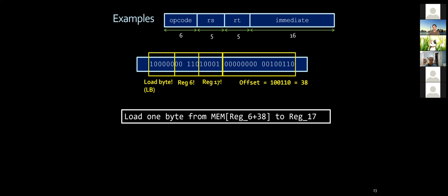But in this architecture, I can read any byte, so the address can be anything. So I interpret the constant for the offset as just a constant, because there's no limitation on being aligned to 4 bytes. In reality, there might be some limitations as well, but here we assume we can load an individual byte.